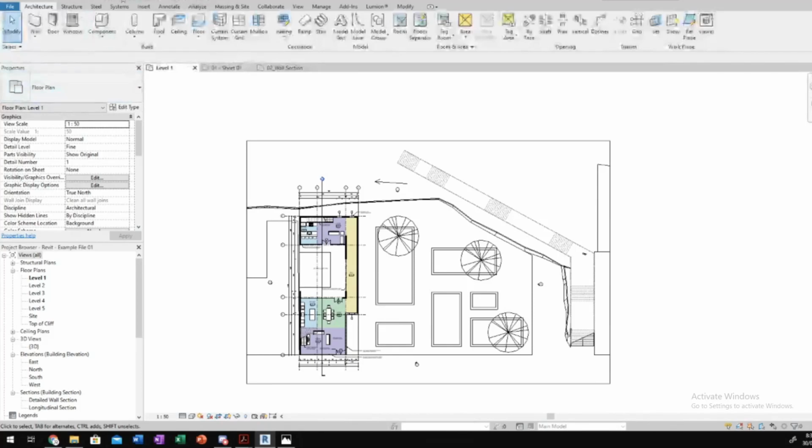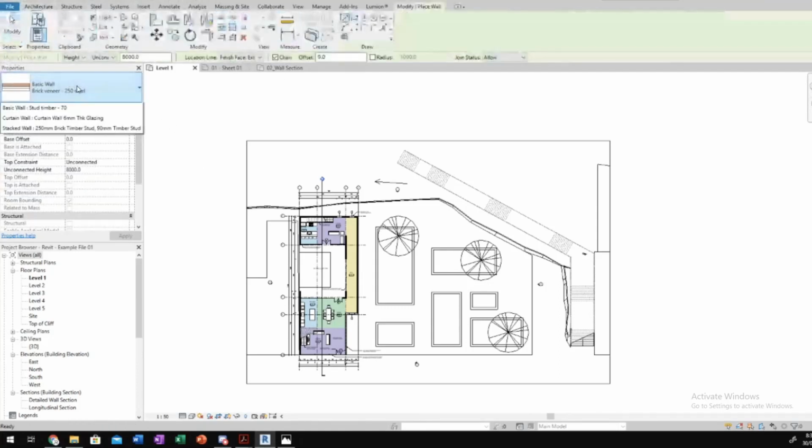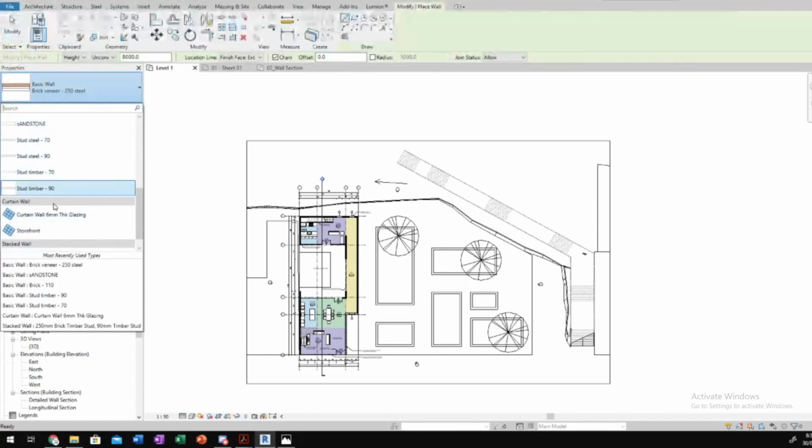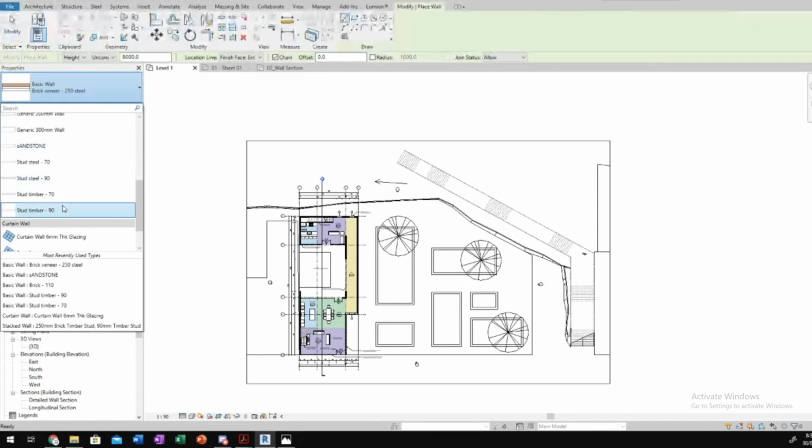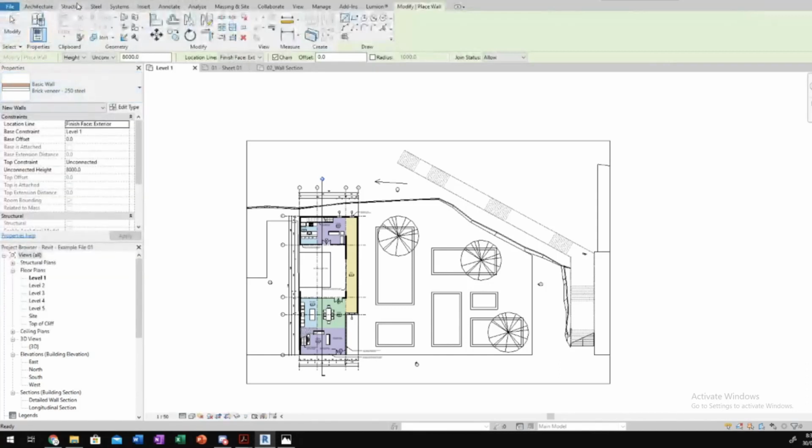So there's a bunch of quick options up here, like the undo, redo, save, etc. And then all of the different buttons that you need to be able to do anything are up here in these different tabs. So with architecture, it's anything that you could build, for example, a wall, door, window, components, which I'll go through later, roofs, floors, stairs. If I click on a wall, then you can choose different types. You can see a list comes down. And then you can start drawing and start building, and you can customize different walls.